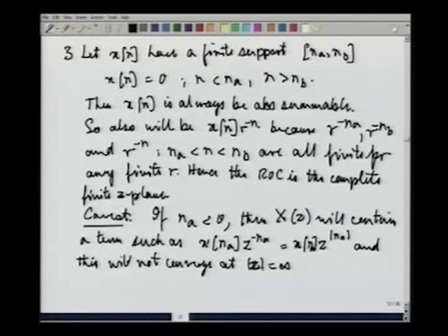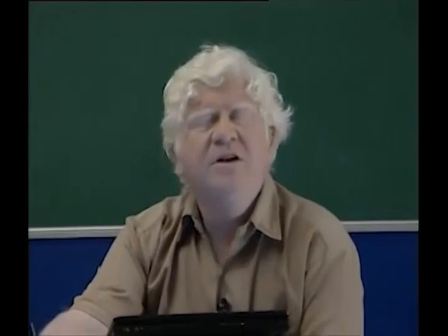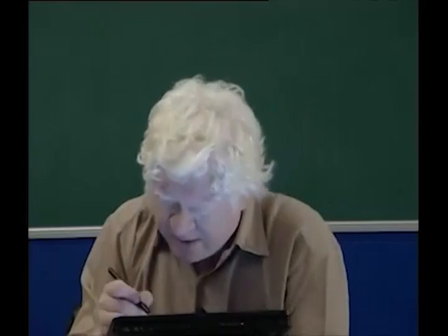Remember that unlike the Laplace transform context, here we include infinity as part of the z plane, as well as the origin z equal to 0. So this has to be taken note of. The finite z plane is completely part of the ROC, but z equal to infinity is not part of the ROC.